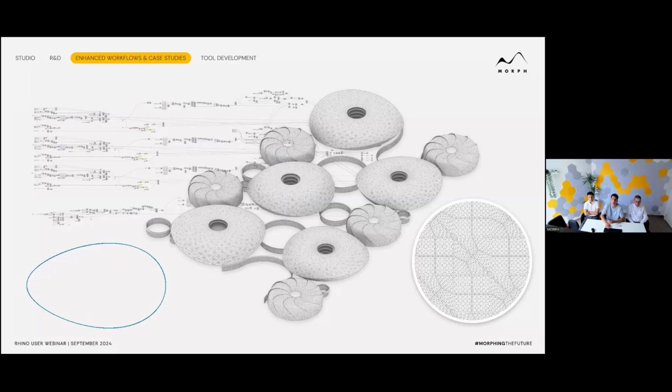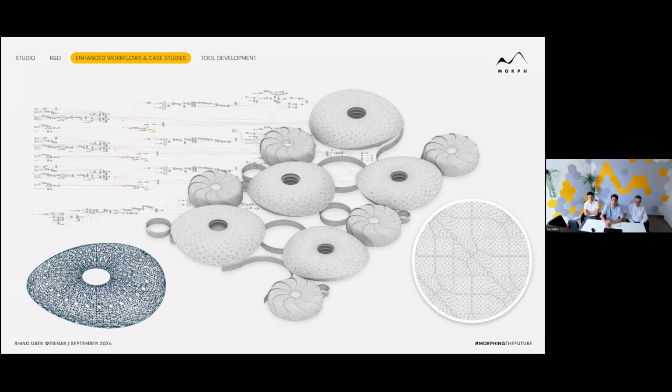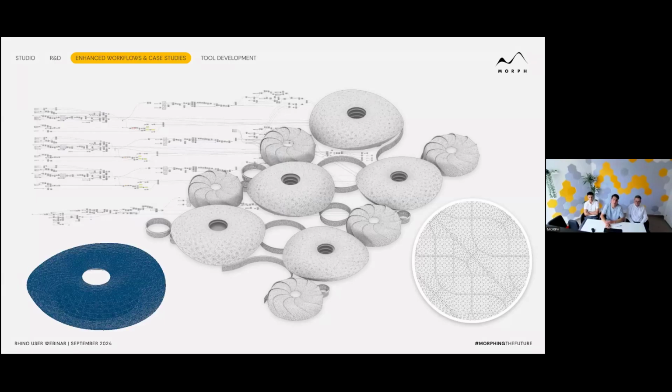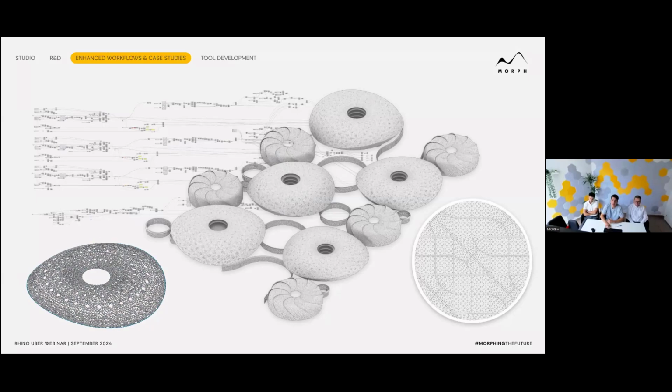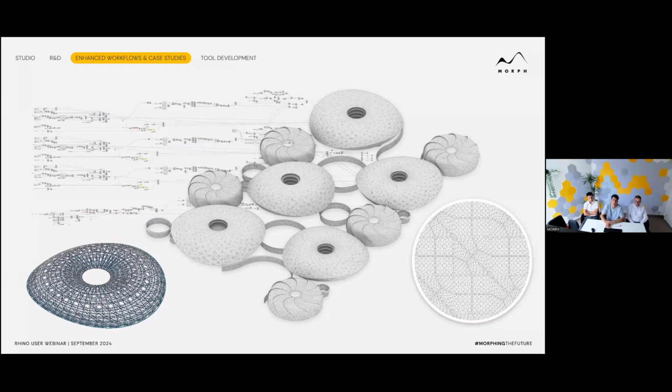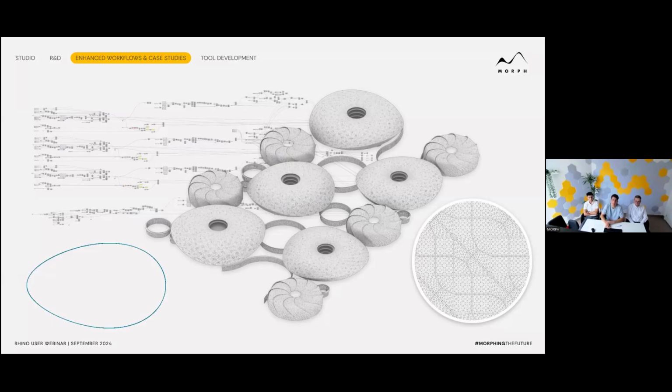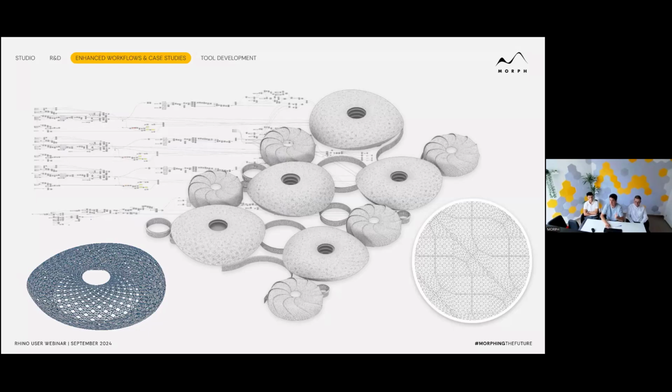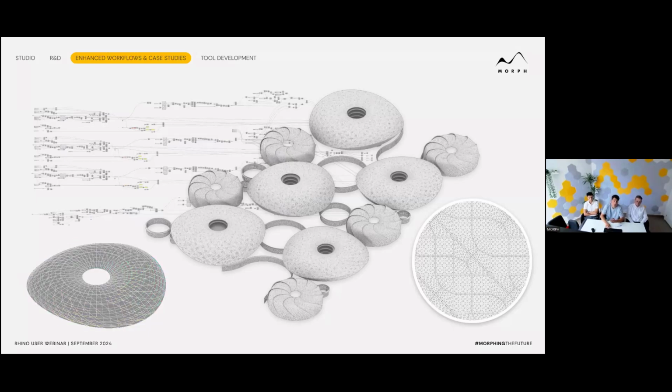We need to explore different design alternatives. And to accelerate this process, in this particular case, we used tools like Weaverbird and Pufferfish, which are plugins for Grasshopper, and are intended for mesh-based geometry modeling, which offer faster results compared to NURBS when the scale of the project is in this range. So in this context, for us, smooth surface transitions were not a priority.